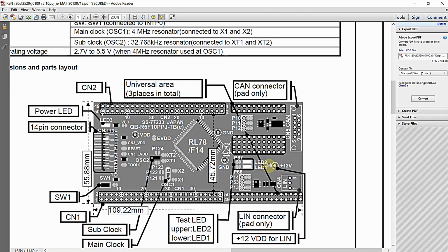we are just going to utilize this particular LED2 which is mounted on the development board, which is connected to the P67 port pin of the microcontroller, for demonstrating the PWM generated from the output pin. So I will be configuring this particular P67 pin as output pin, and we will be demonstrating the PWM wave generated from the timer module of the microcontroller with the help of this LED2 mounted on this development board.